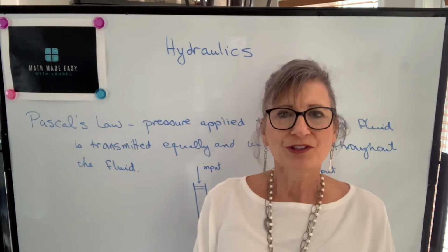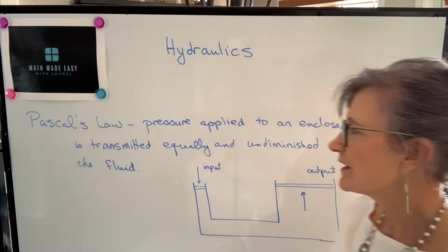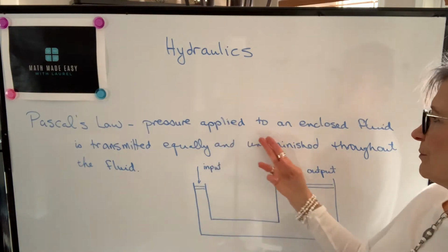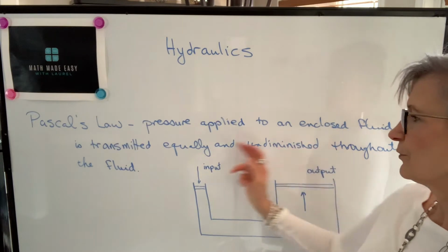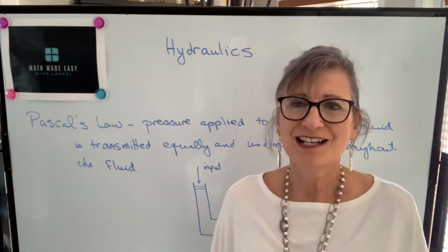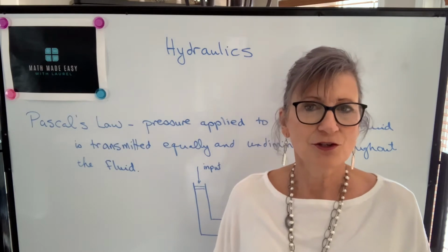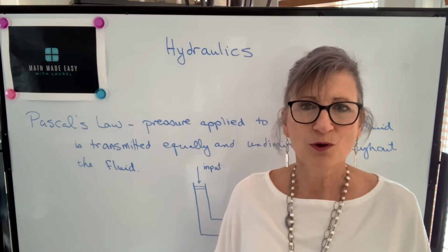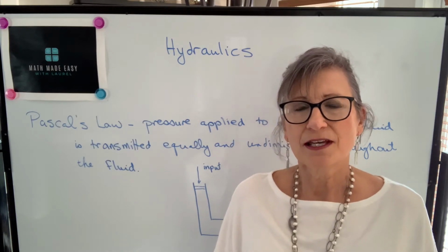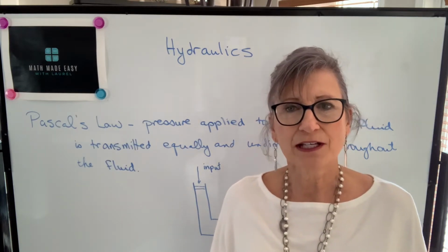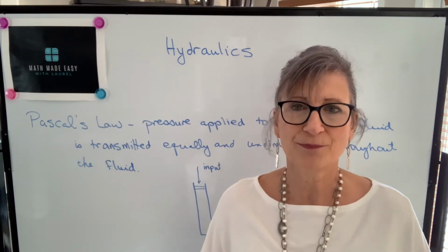A very important concept when we're talking about hydraulics is Pascal's law. Pascal's law states that pressure applied to an enclosed fluid is transmitted equally and undiminished throughout the fluid. This principle is put to good use in a number of different ways: hydraulic brakes on a vehicle, hydraulic hoists, hydraulic jacks, hydraulic presses, a number of ways that we can increase the mechanical advantage, or in other words, increase the force that is moved or carried.